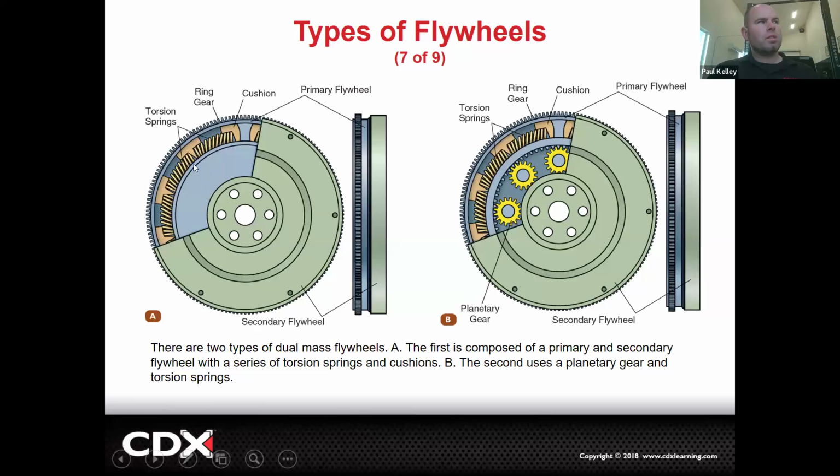If those pulses are transferred to the spring and the little cushion, the rubber bumper, it's going to smooth it out, and your actual clutch plate, your pressure plate, is really only going to touch the friction surface, which has already been pre-smoothed out. Makes sense? So the dual mass flywheel makes the clutch get a really nice, smooth, not power pulse, not harsh, clean feel, and that does make the car feel more smooth.